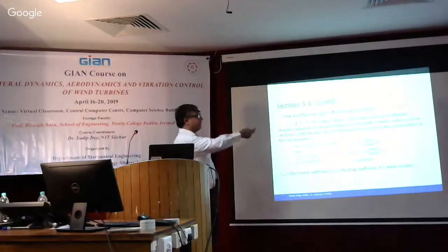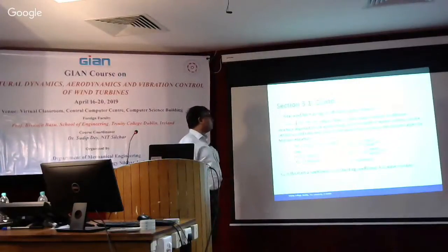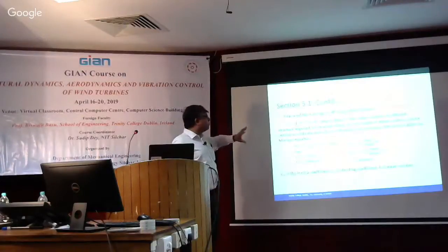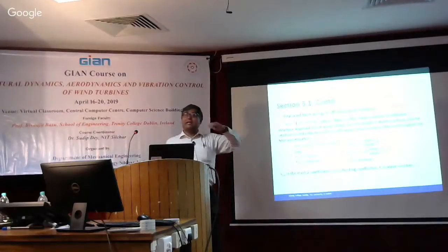But when we analyze the wave loading on the wind turbine, this is essentially how we connect the wind to the wave. So it's through U10 that you can connect the two. Now you take the U10 and use that in your wind profile.